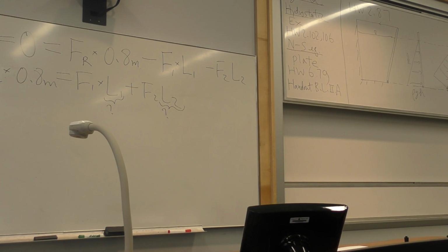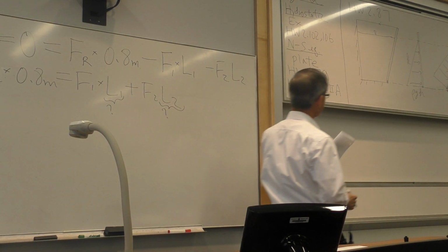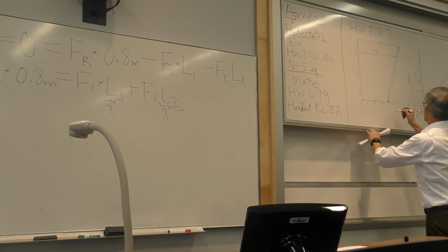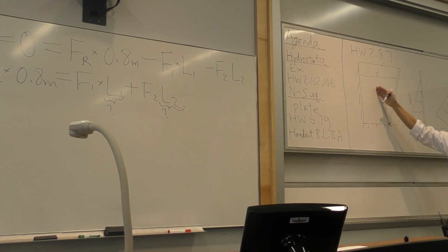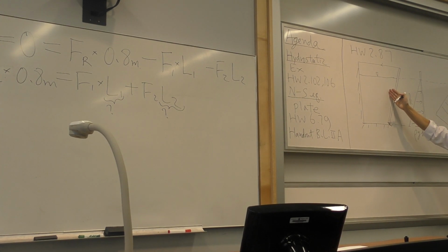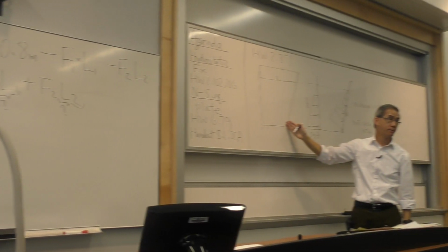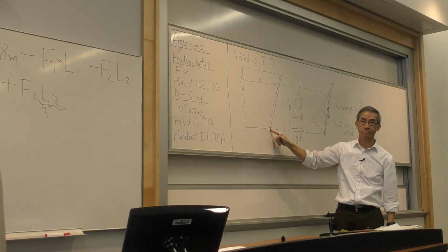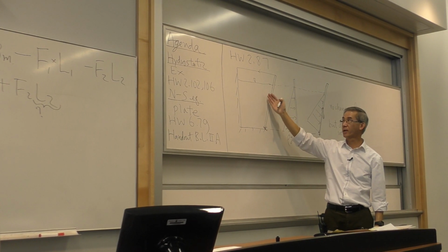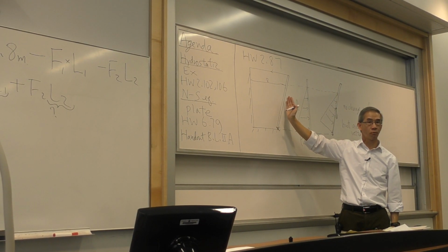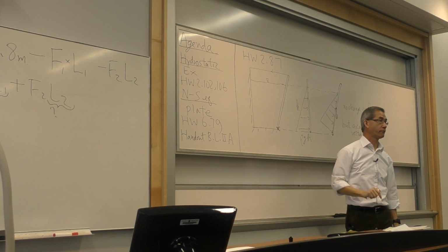The only reason I get the force due to the water alone, just like you did for homework today, which I still have on the top, is because I need that to get my moment. How did you do this problem? You get the water force due to hydrostatic acting on this plate, and then you take moment about here, right? So step one is find out the force alone due to water. And that's what we did in the first step.